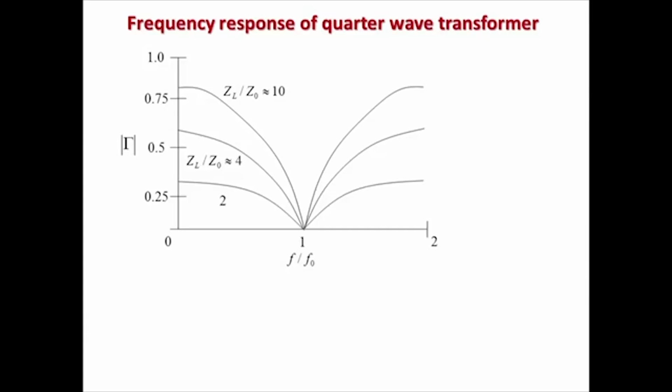So, you will get a very sharp frequency response, but instead of one section, if I have multiple sections, then the whole thing can be improved, because each section is seeing a smaller change of load and source impedance, and then its match will be broader. So, the overall sum total match will be much broader, very near to 100% bandwidth sort of thing.